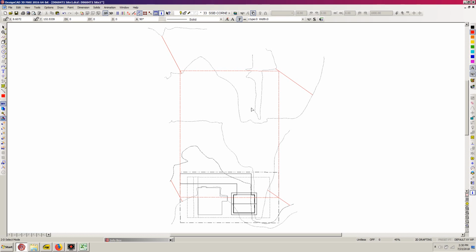I need to know what that total slope is, and as these are sloping to the north, they'll be minus figures, and that's really important. If you're sloping to the north, it'll be a minus figure. Okay, so what we're going to do is find out what percentage this portion of this line is of the whole thing. So this is the portion that's actually in our lot. So that's the portion that we're interested in.